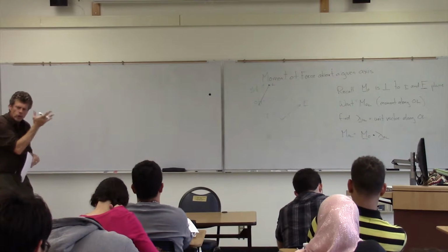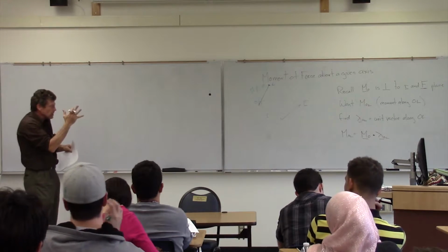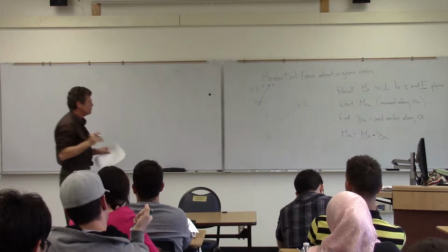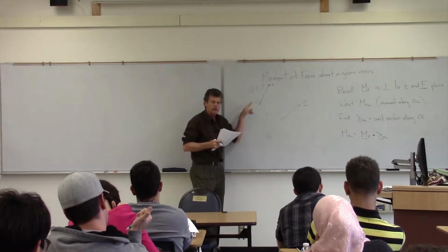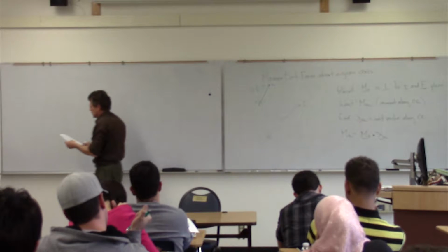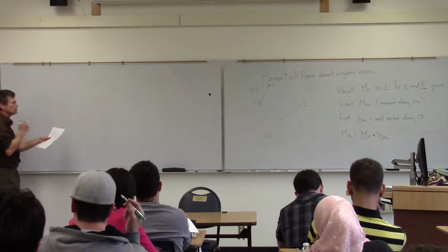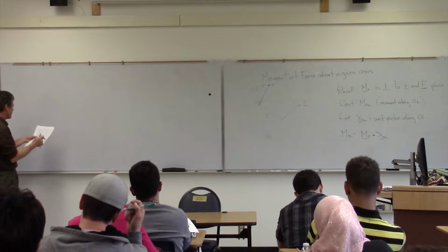So this is the tool then we use to basically do this projection to determine the moment along this line OL, and then as a designer we can figure out how much weld or how many bolts we need to put in that particular place.